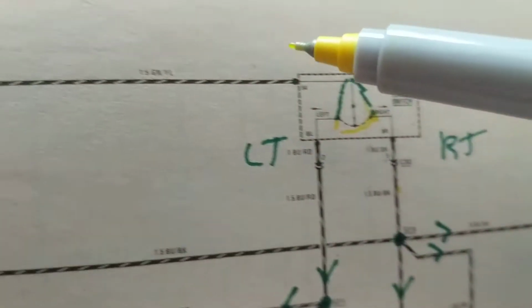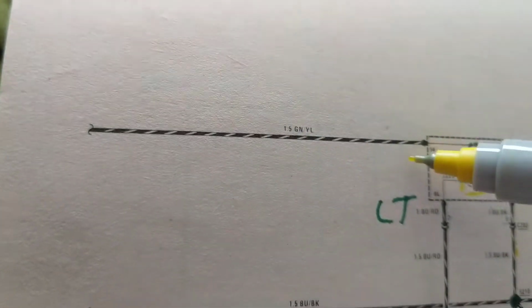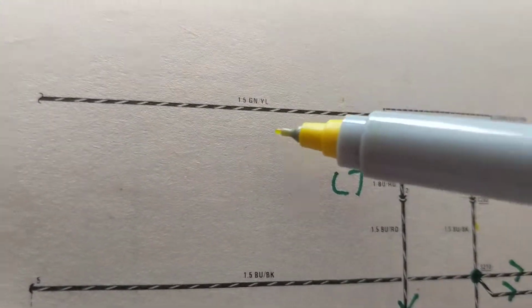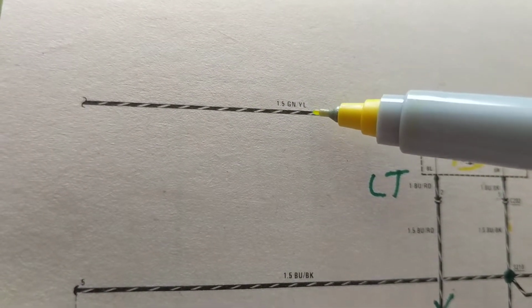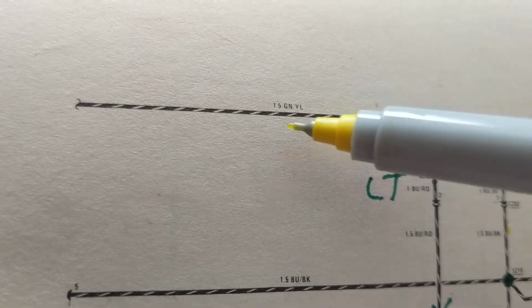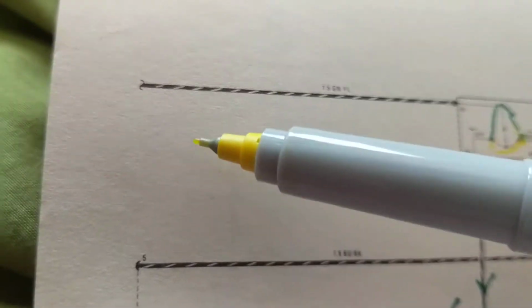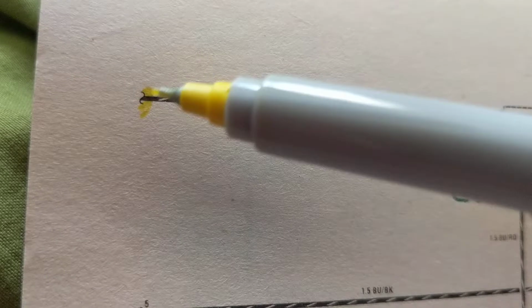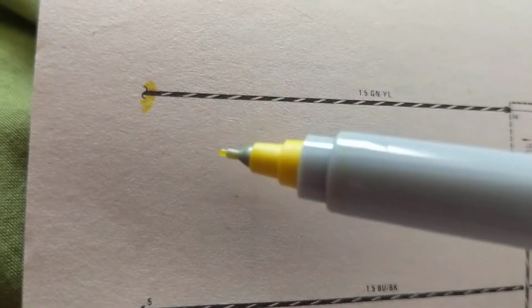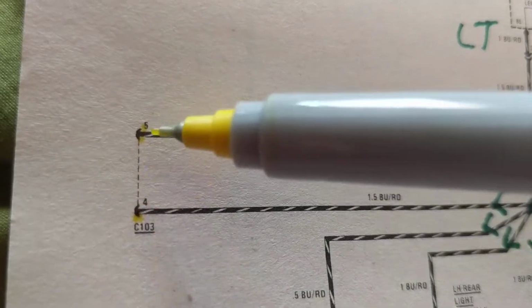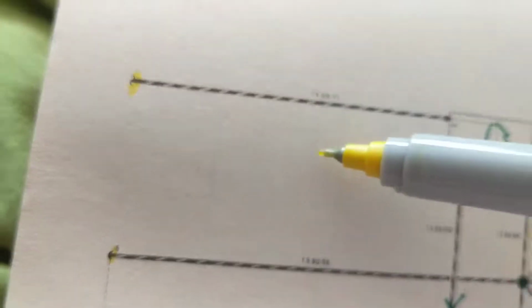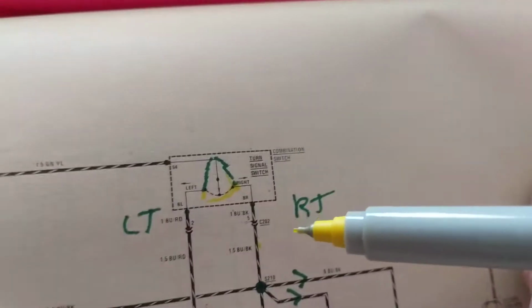Therefore, this, we see no B+. You're not going to always see a B+ or a battery symbol when it comes to automotive. You will see it in other schematics, but not in this. The fact that you see this little wing over here, I don't know if you can see it, means there's a connection to somewhere else. See this and this? That means there's a connection to somewhere else. Somewhere on another page is another part of that schematic.